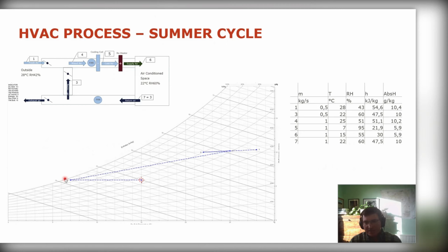That's what would happen in an ideal scenario. In reality, that's not quite what happens. Instead, as you can imagine, some air goes really close to the coil surface, and therefore it's in contact with a surface that's below its dew point, and it starts to condense straight away. On the other hand, air that is slightly further away doesn't condense. So on average, the whole air cools down, the whole air becomes slightly drier, but the way that it works is that you start squeezing some moisture out.